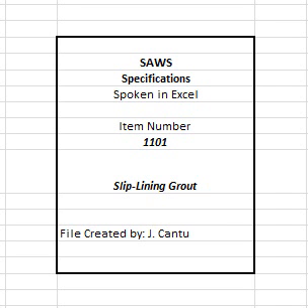2. Equip slip liner pipes with weirs to fill the pipes with water to prevent flotation during grouting operations. 3. Remove or control standing or running water in annular spaces to maintain the correct water ratio of the grout mixture. Grout the annular space by injecting grout from one end of the pipeline segment, allowing it to flow toward the other end. Vent the annular space to assure uniform filling of the void space.